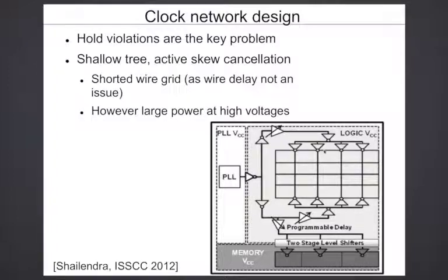They'll all be within a gate or a fraction of a gate delay. And when you have these signals which are off by a fraction of a gate delay, and when you short them, the output edge will actually be a degraded edge, but it will be in between the two edges. Imagine that you have two inverters which are giving an output which is off by a small number, say that difference in delay is maybe 1 gate delay. When you short the two outputs, the output now will, in some sense, interpolate. The actual edge will be interpolated between the two edges.